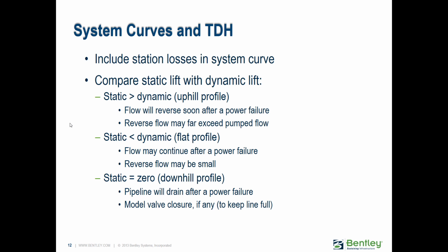So you have a static lift, which is basically the difference if you're dealing with pumping from one boundary condition to another, like one tank to another. You have the static head, which is just the difference in the hydraulic grade of those two boundary conditions, and usually that's uphill, but sometimes may actually be downhill if your dynamic losses, your friction losses, are high enough.